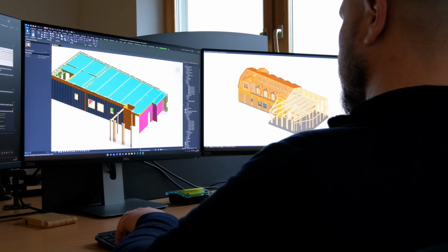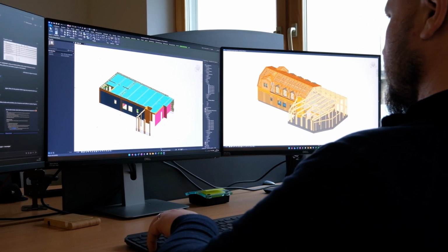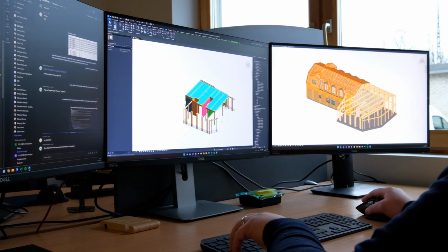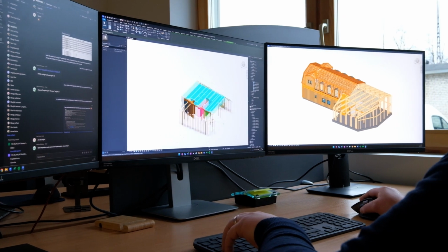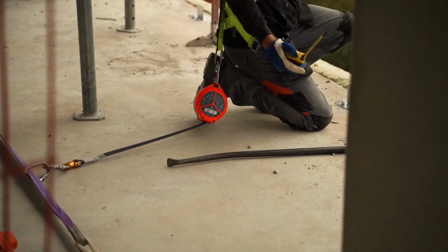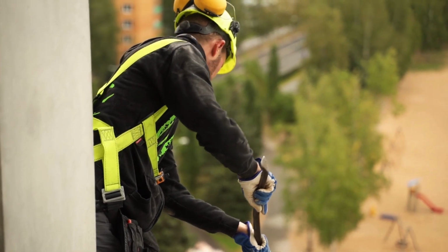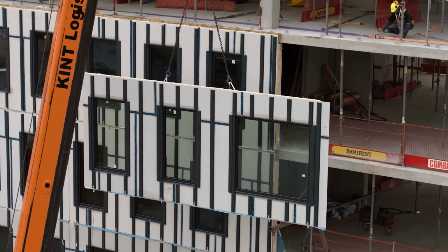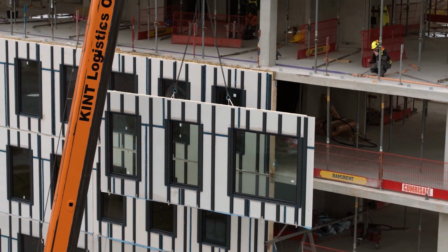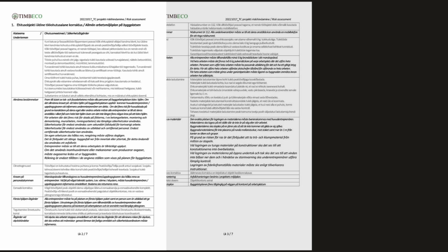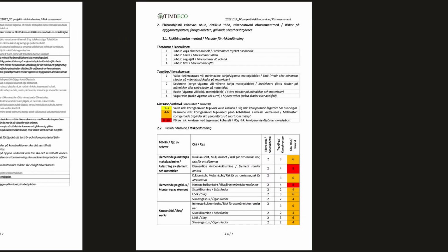Risk assessment and risk analysis begin in the design phase of a building. It is crucial to consider how to complete the project as safely as possible from the outset. When evaluating potential construction risks, designers must also plan for safety measures. For instance, if work at heights is anticipated, it is necessary to plan for the use of appropriate safety equipment. Anchor points that can withstand the expected load, and where safety gear or guardrails can be attached to prevent falls, are planned for. A separate risk analysis is prepared for construction site activities, considering all site works and their specifics.